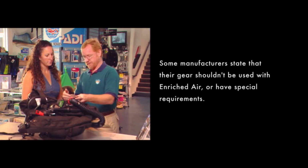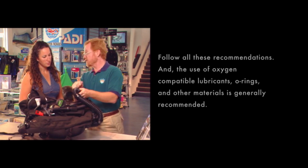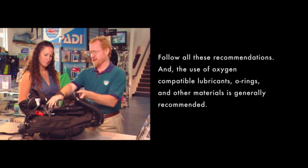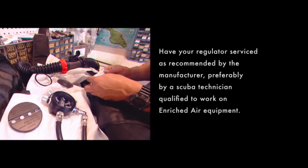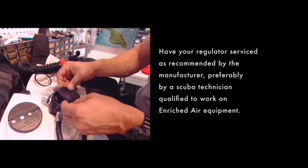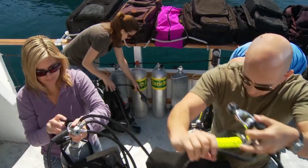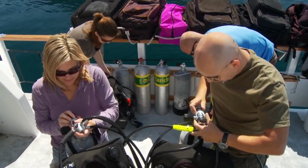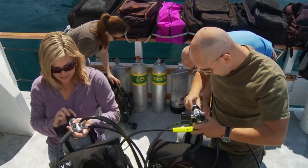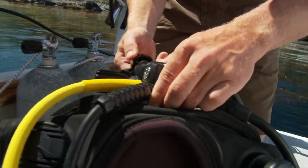Some manufacturers state their gear shouldn't be used with enriched air or have special requirements. Follow all these recommendations, and the use of oxygen-compatible lubricants, O-rings, and other materials is generally recommended. Have your regulator serviced as recommended by the manufacturer, preferably by a scuba technician qualified to work on enriched air equipment. If your equipment is accidentally exposed to anything other than water, such as oils or lubricants not recommended by the manufacturer, have it inspected or re-cleaned by a qualified technician. If you add any accessories, such as low-pressure hoses, follow manufacturer recommendations.